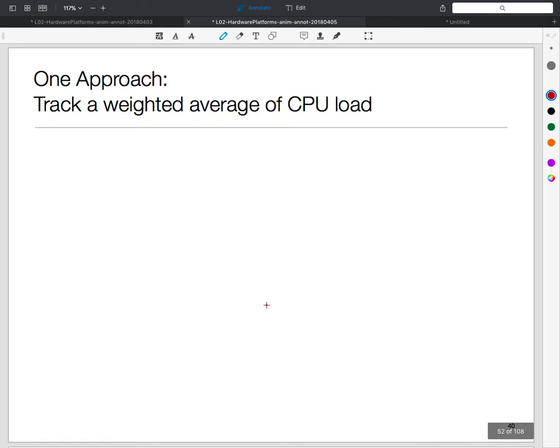So how do we manage this process if I have these big.little? How might you do it? One approach, which I very loosely mentioned earlier, is I keep an eye on how heavily loaded my processor is. And if the processor is getting close to its full capacity, then I would say, aha, it's time to wake up the big guy.